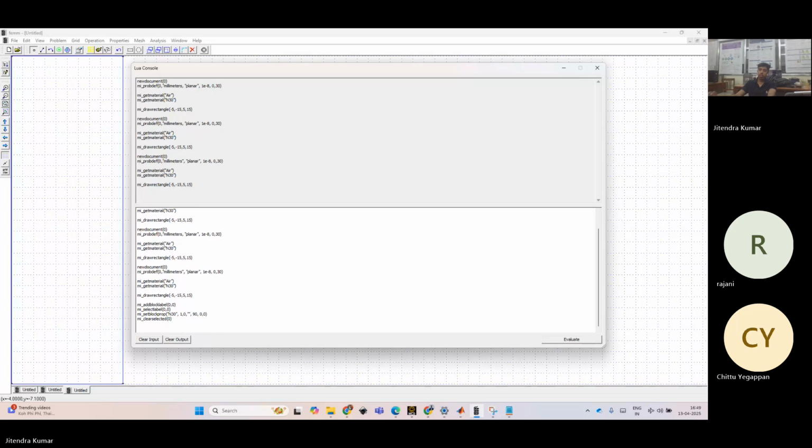Now, this is a magnet, but to observe the impact of the magnet, we should also have some air inside. So we have to create a boundary with an air region. Okay. So for air also we will have similar things like a rectangle. So we have to draw a rectangle again. We will just copy this line and draw a bigger rectangle, right? Since it was -5, 15, means 10 and 30 mm, we will create almost double or triple of that, right? So that should be like 50, 50, 50, 50.